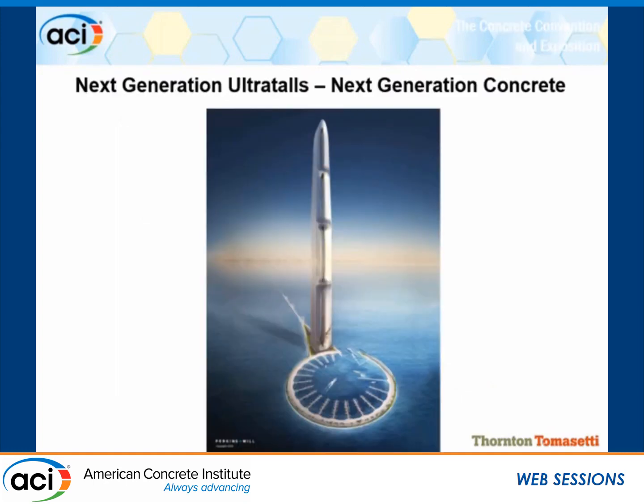And one thing I'll just very quickly mention. We have buildings on the drawing tables even today that are much taller than the ones that have been built. And they're in various places around the world, a few of them in Chicago that will be taller than anything that will be there today. So the issue of modulus of elasticity is not going to go away. It's here to stay. It's only going to increase, and the need to have mixes that can reach target modulus is extremely important for us as engineers of tall and super tall buildings.